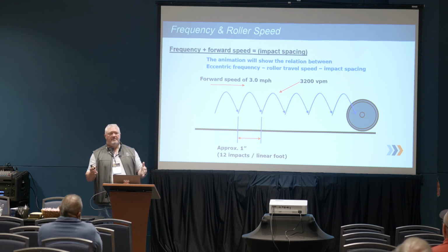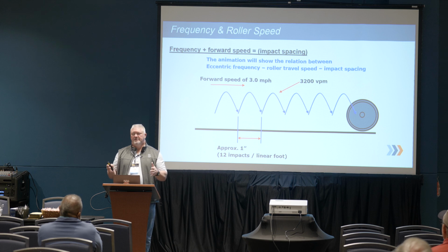I always tell people if I can maintain between 12 and 16 impacts per foot, I don't care whose roller you have, what size roller you have, you should be able to achieve the compaction and rideability you need if we stay within the certain temperature range we're trying to achieve.